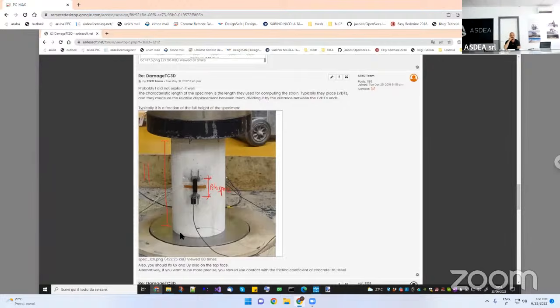But also in reality, when they give you direction for creating these specimens and they decide a certain size, is that because they know that this size should be sufficiently large to capture the fracture process zone, but should not be extremely large, otherwise it will be brittle, because the size effect is also happening in reality.